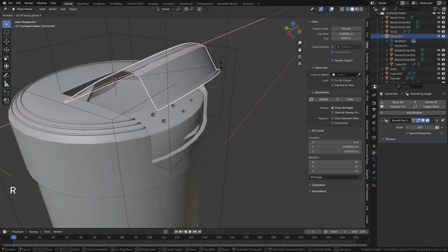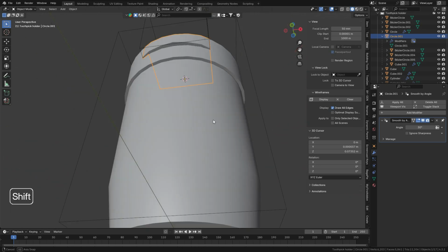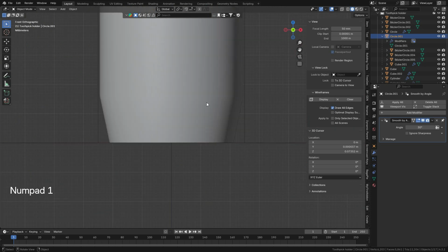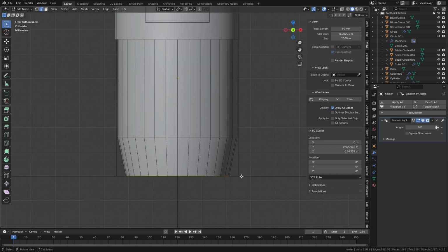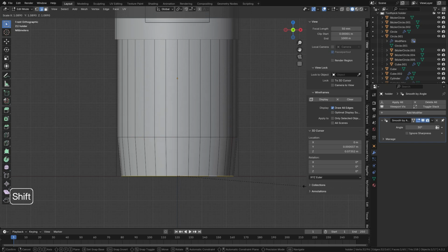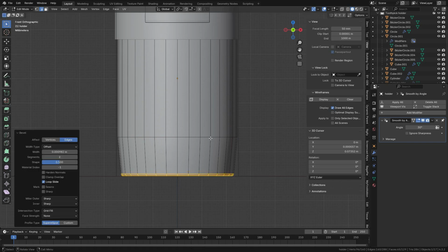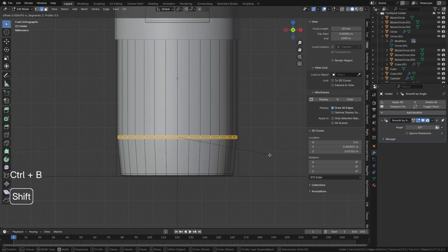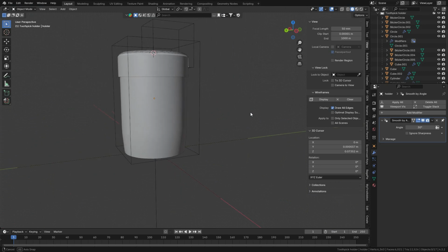We are going to try and rotate this back. Yeah, so about everything is okay. What you just want to work on here is the bevel for the body. Then I think we are done for this part. Go to edit mode, select this, scale this up just a bit. Okay, fine. Press Ctrl B and just a little down here, should be about okay. Select this edge, bevel this as well, about two loop cuts in there, should be okay. Then left click, go to object mode, and I think we have a toothpick jar done.